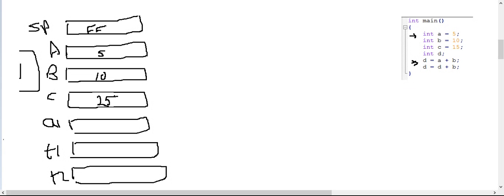You do that by pushing the return address and pushing the values of all the registers you changed in the new function. So if you have another function that is going to use registers A, B, and C, you'll need to push them on the stack before you change their values. We're gonna have an example to demonstrate that in just a moment.